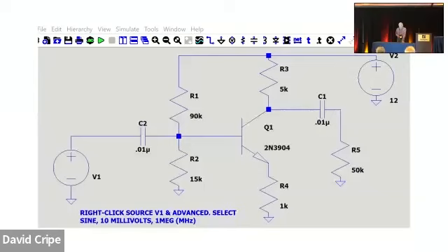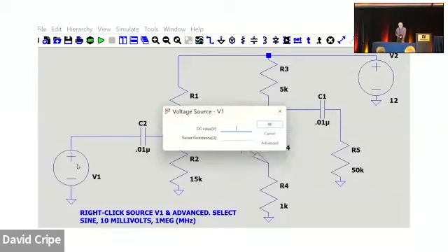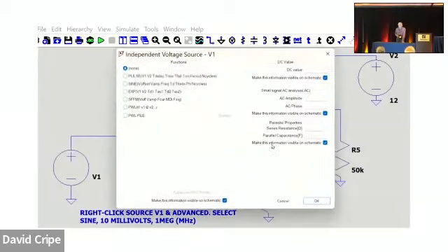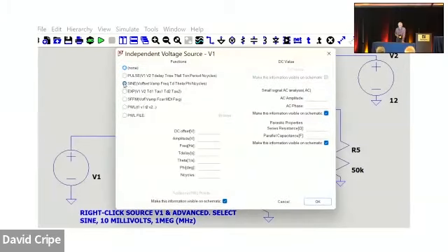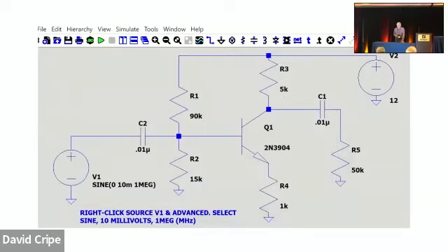Okay, now I think this is where I'm going to create the voltage source for drive. I'm going to hit Advance, choose Sine Wave, put 10M. That's 10 millivolts. That's peak, not peak to peak, not RMS, for that sine wave. Frequency, I can't read it. I think it says 5E6, 5 megahertz. But anyway,